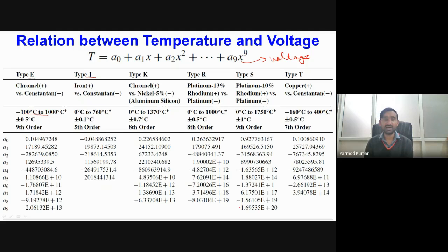Okay, so that's why, if you have used thermocouples earlier, you will know that depending upon the type of the thermocouple, many times we have thermocouple type specific post processing units. Or apart from that, we also have some generic data acquisition systems or generic temperature processing units, inside which we have to select the type of the thermocouple we are using. So we have to specify the input that this is the type of thermocouple which we have physically connected to the channel.